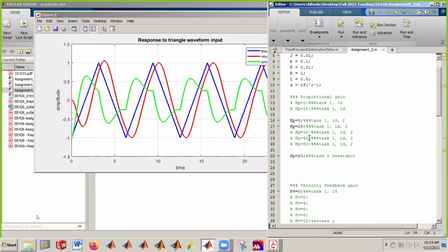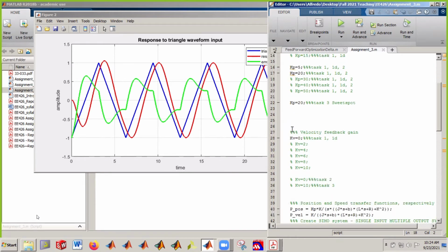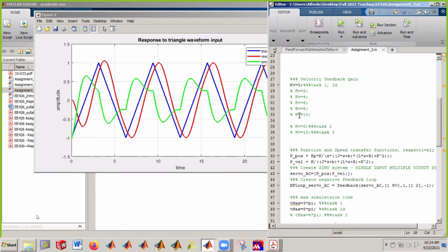It is a very effective tool, but just like the KP gain, when you have too much of it, you will just slow down your system too much, and then it defeats the purpose of using it. So there's always a trade-off with these techniques. They are very effective for particular cases, but they are not universally valid. And that is something you will see for the PID. This is why the PID needs to be tuned to the particular application or system you're trying to apply it to.